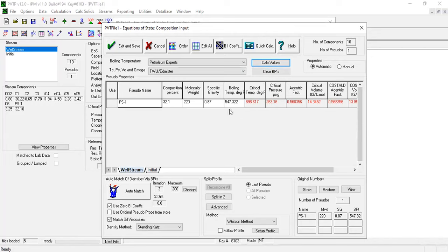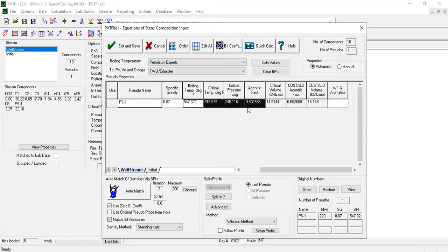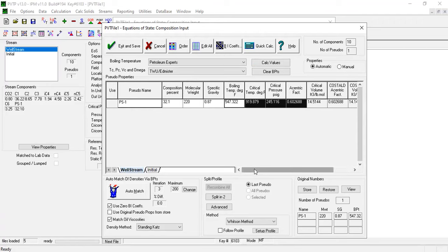Okay, so now this is the current condition, and we will press Automatch again to ensure the calculated liquid phase density is realistic. After clicking Automatch, now we will have these results. Now we will perform quality checks, which is again the separator and phase envelope calculation, to compare the calculated results with the measured results.